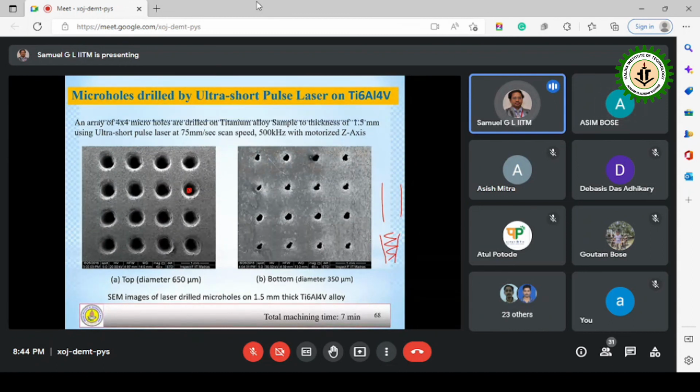Yeah, but what we are making is actually what they call tight focus, where you make the spot diameter as small as possible, so that we can make the light go around like this, and we can remove the material. So this is trepanning. Conventional technique calls it a boring operation. Enlarging the hole slowly. Yes. So here we send the laser light along the periphery, or the circumference, of the circle.